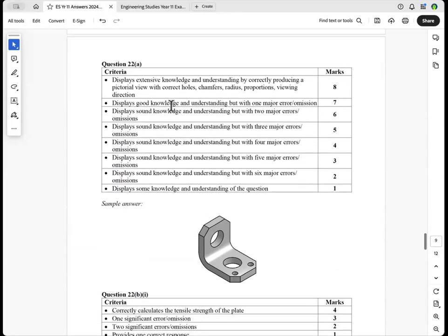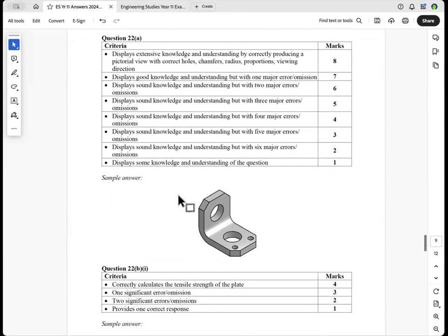So this is the solution there. I'll just go through a couple of things that people didn't do correctly. Some of you didn't put the curve down the bottom. Some of you didn't put the 3D holes down there. Some of you had the wrong shaped holes. Remember, there are 3 sorts of ellipses on an isometric drawing, but generally it was done reasonably well.